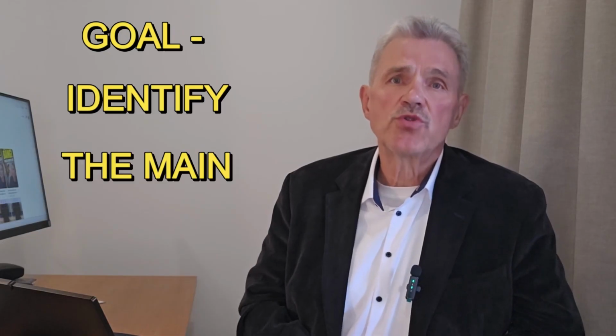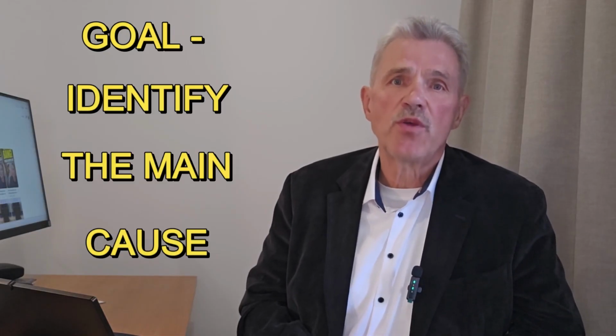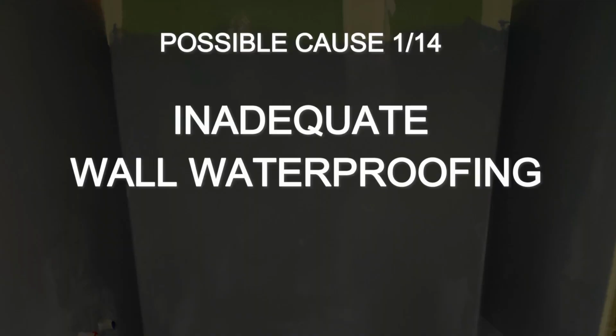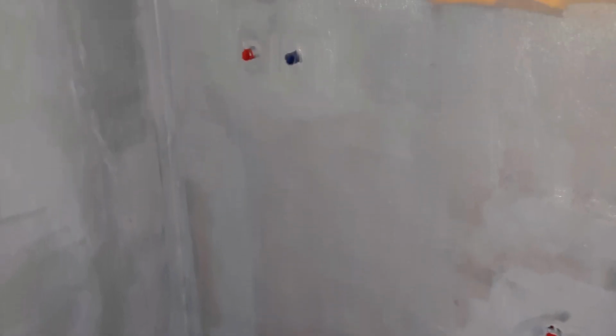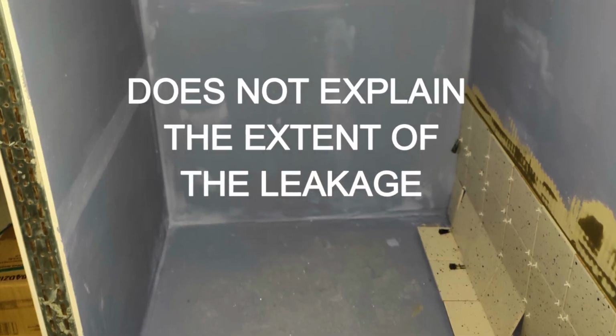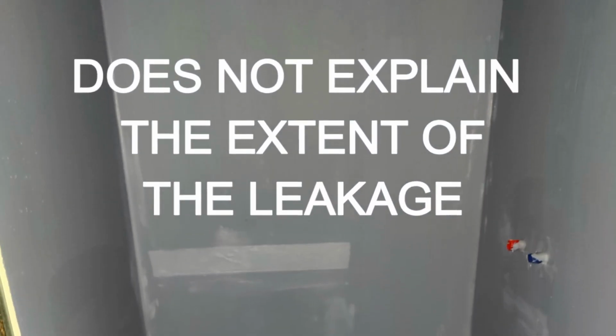So it was necessary not only to identify the defects, but also to determine which of these defects caused the water leakage. The first version, too small an area of wall waterproofing. In the construction photos, it was visible that by the shower, the waterproofing was not installed to the full height of the wall in all places. Because of this, certain parts of the wall could have been less protected from water splashes, but this circumstance could not explain the scale of such a leak.